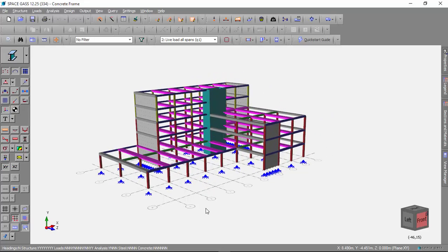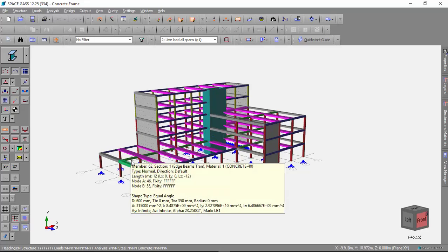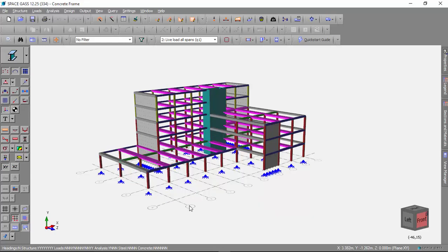So we'll just go ahead and design some of the beams in this one just to show you how that's done. As in the column design module, you need to specify your cross section first. The design module won't change your cross section, it will only specify the reinforcement. This model has got slabs spanning two-way, and we haven't actually modelled the slabs, we've just modelled the beams as T-beams and L-beams that are supporting the slabs, and applied the slab loads as area loads to those beams.